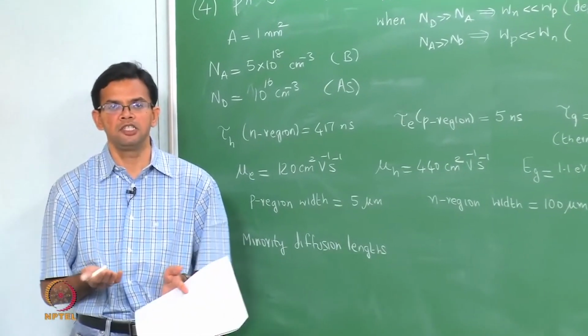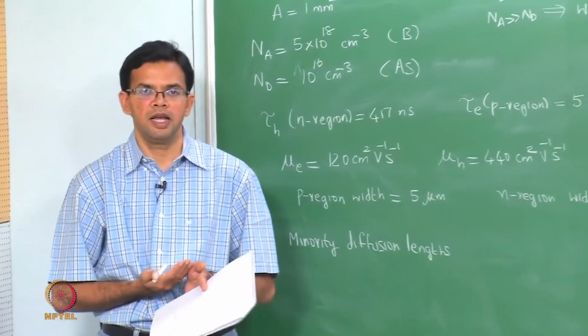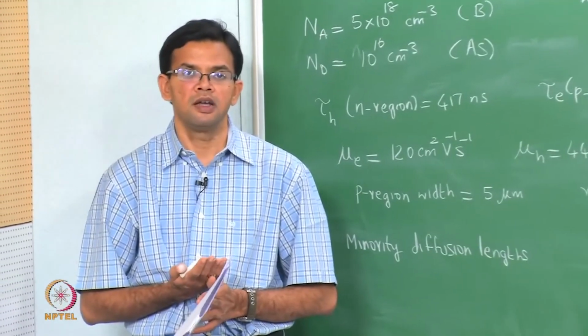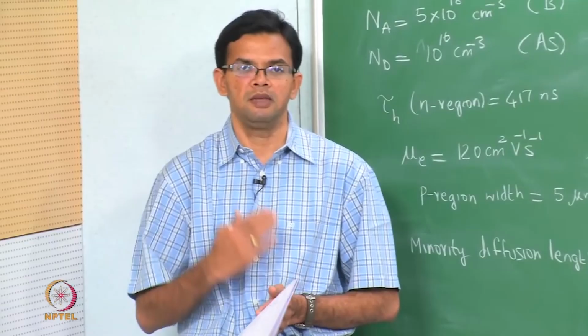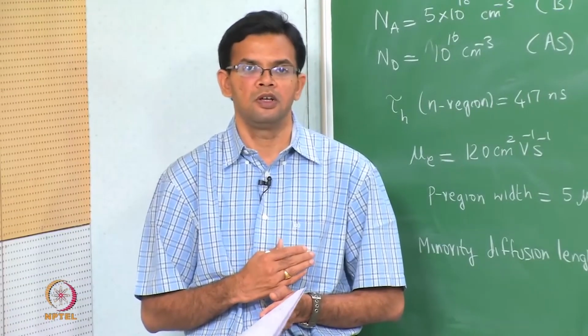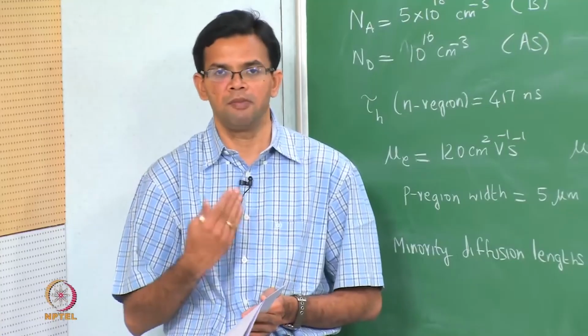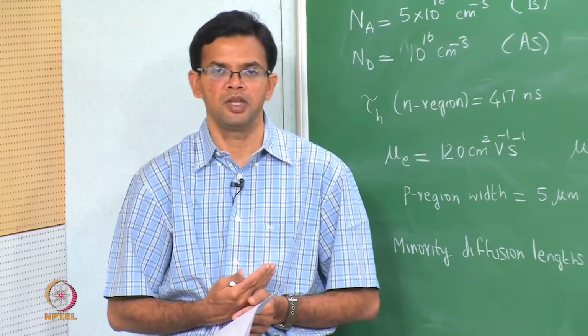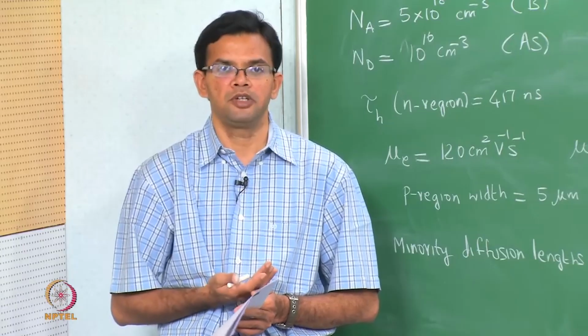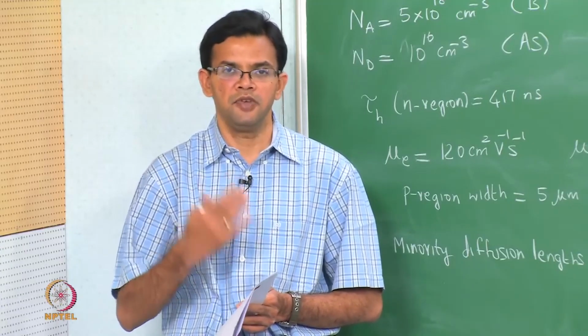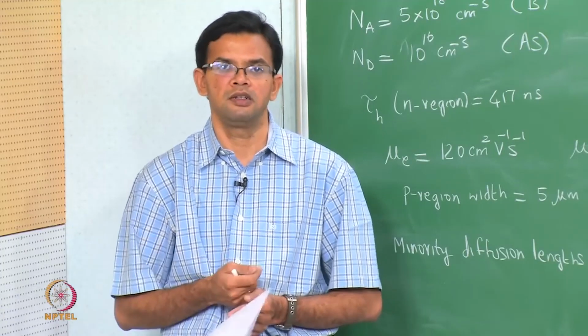The Fermi levels no longer line up, but essentially get shifted, and when this happens, the barrier comes down. So, V naught is the built in potential or the barrier during equilibrium. When you apply an external potential, the barrier is V naught minus V external.